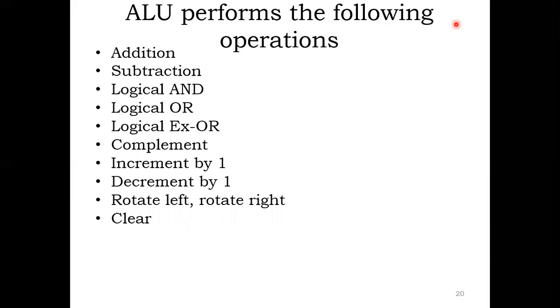These are the operations performed by the ALU: addition, subtraction, logical AND, logical OR, logical XOR, complement, increment by 1, decrement by 1, rotate left, rotate right, and clear. In this list we don't see multiplication and division. In the 8085 we don't have multiplication and division operations.